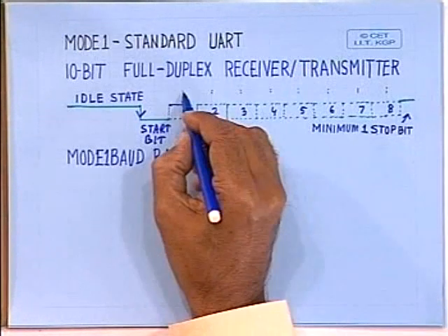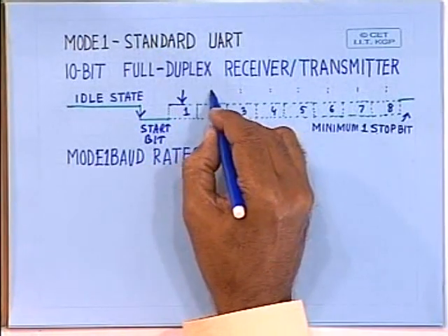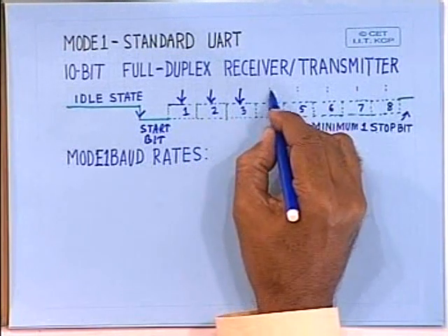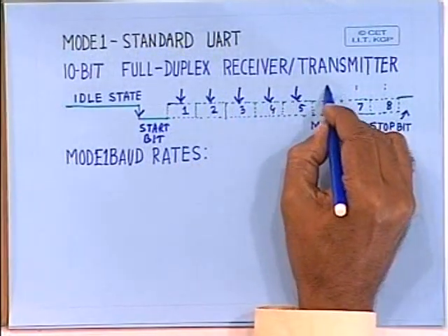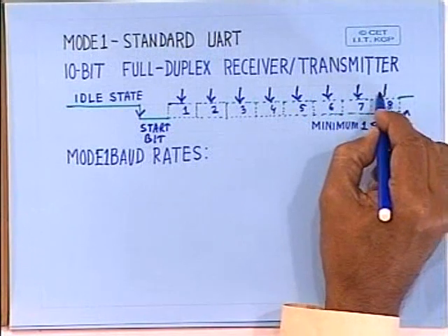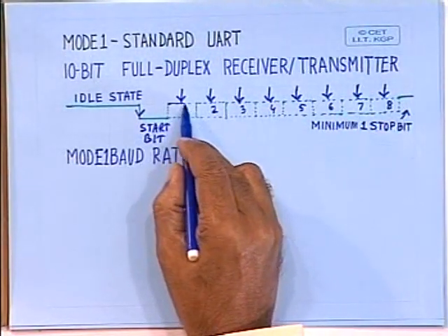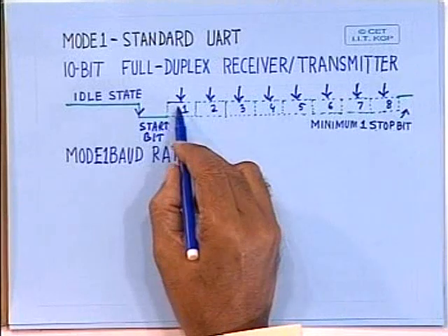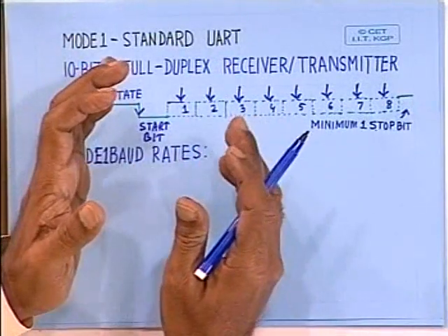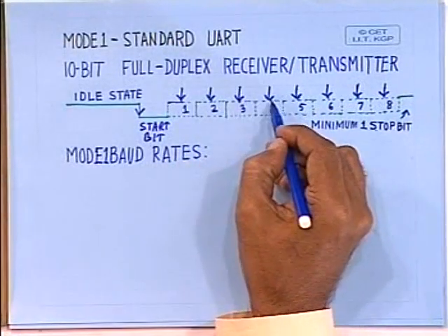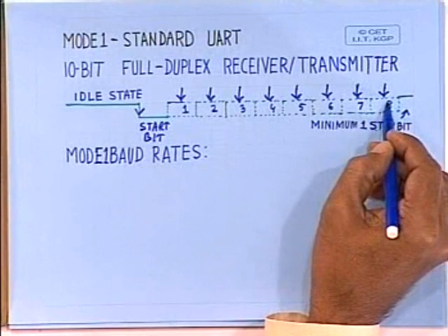And at the receiving end, the shifting in of data takes place in the middle of the clock period. As a result, since you are sampling data at the middle of the signal, this allows you to have a small difference in clock frequency between the transmitter and receiver, and also, because of glitches and other noises, false data transmission is avoided because of this reading of data in the middle of the bit period.